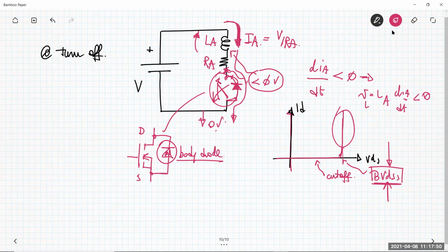Okay, so you always have to operate your MOSFET for a voltage V which is less than the breakdown voltage. This is for sure. This is a region in which you cannot operate safely, because if you go there, when the voltage is exactly the breakdown voltage, it happens that the energy dissipated is so high.